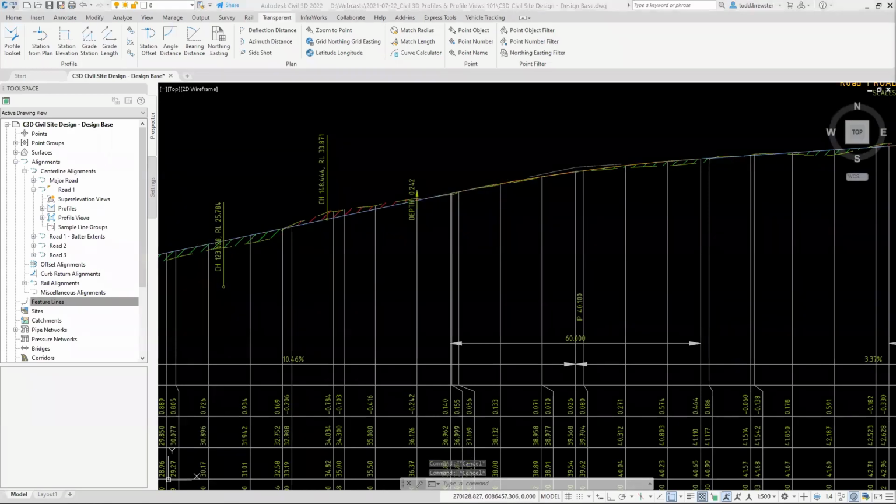Okay, let's have a quick look at projecting data. So you can project a few different things into your profiles. You can project AutoCAD points, blocks, 3D solids, 3D polylines. You can also bring in Civil 3D Cogo points, feature lines, survey figures. You can even bring in bridges that you might have done through InfraWorks. And then the way they're represented in your profile is actually via styles.